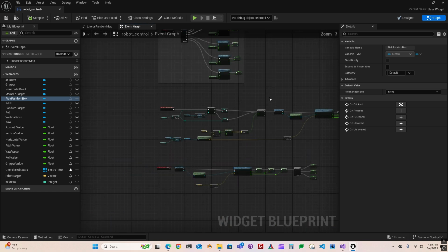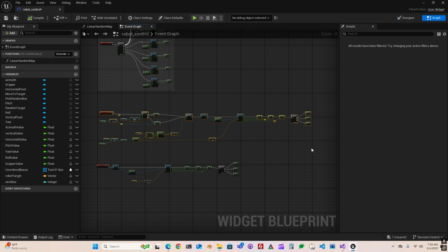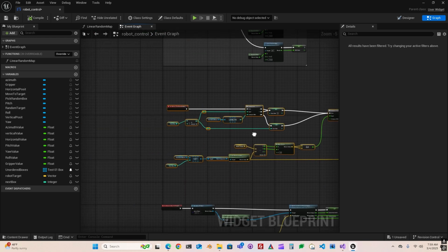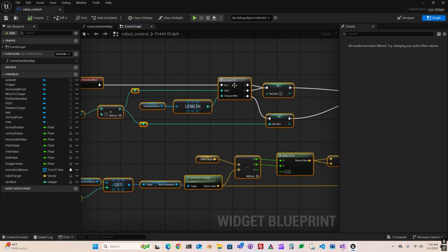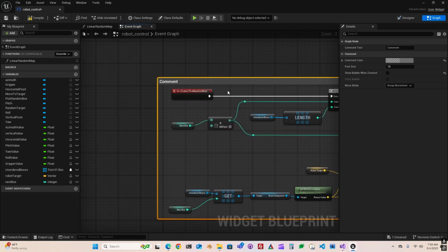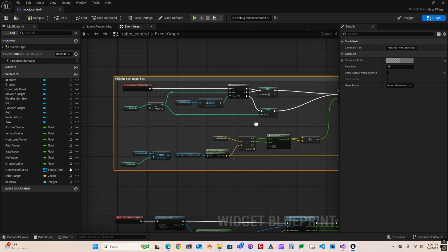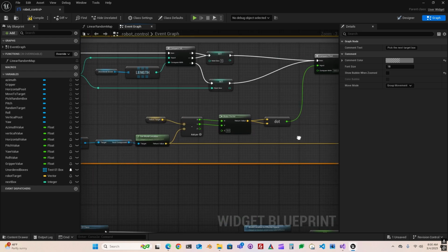Next, we add a script for moving to the next box in the array. The robot moves toward the next available box that is not already in the target destination. All the scripting uses standard blueprint scripting nodes. The only caveat is obstacle avoidance consideration. Instead of moving directly to the target box, the robot first moves above the target to prevent collisions, e.g., when stacking boxes. The final adjustments are made manually using the sliders.